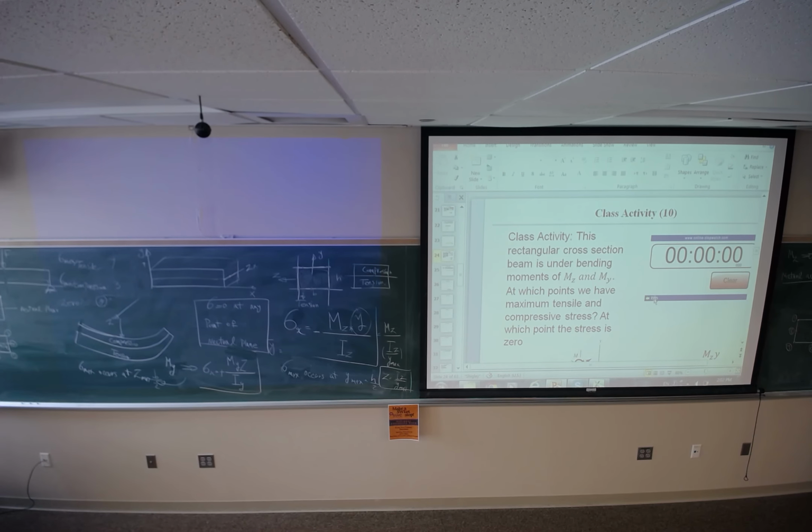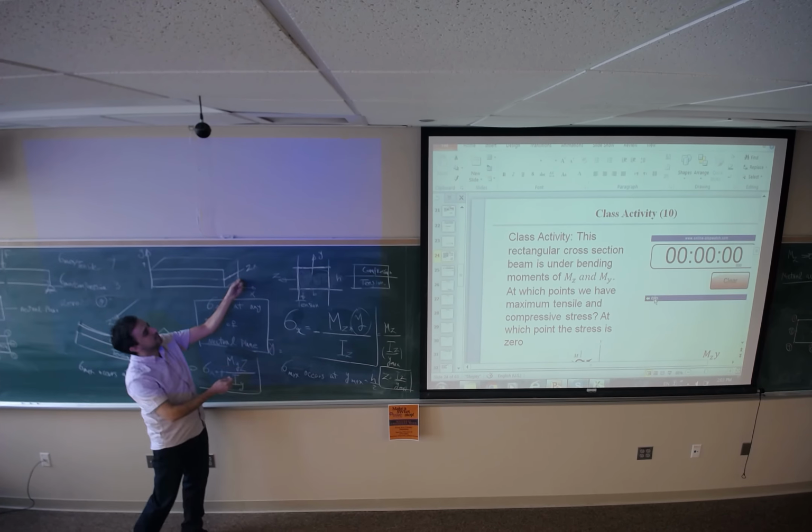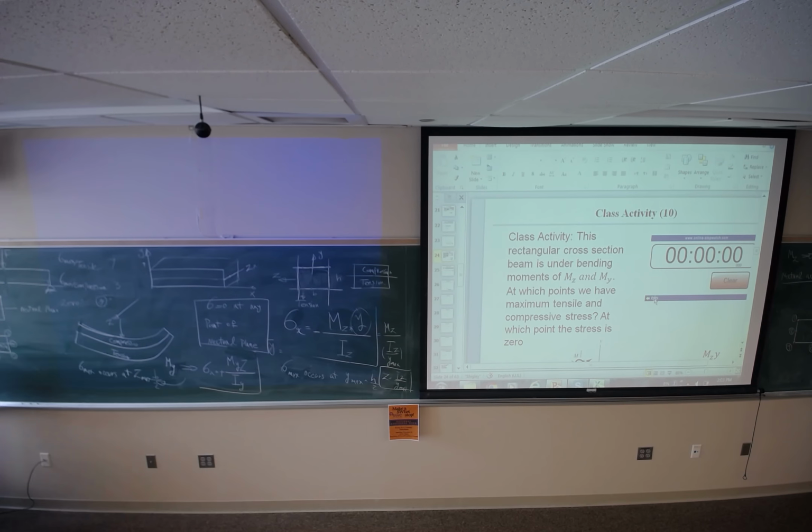Good. This is important because in some mechanical components like a beam, you might have different loading and different bending moments. Then you should figure out which point is going to be the critical point, or where failure, if it is going to happen, will occur. So it is going to occur either at point 3 or 7.